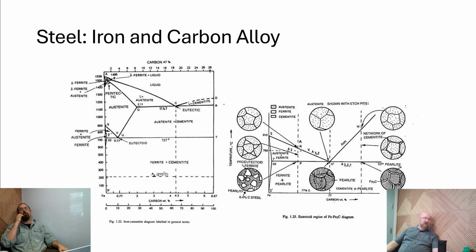The other thing to point out here is that, again, remember that the material properties that we've been discussing are neutral. There are times when cast iron is the appropriate material for an application, and it outclasses everything every time. One characteristic of cast iron, because of its behaviors, is that it's very dimensionally stable compared to steel or lower carbon alloys, which can expand and contract quite a bit with heat.